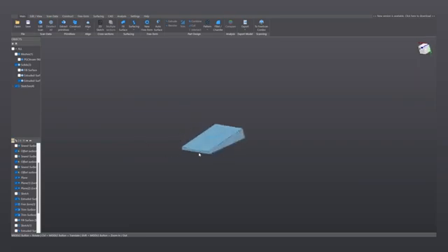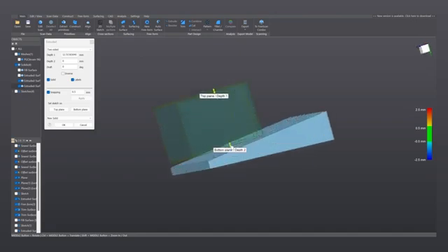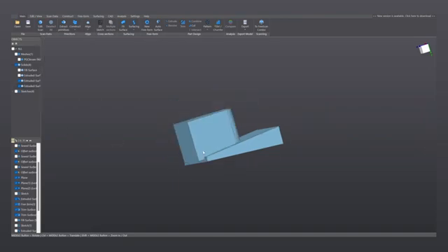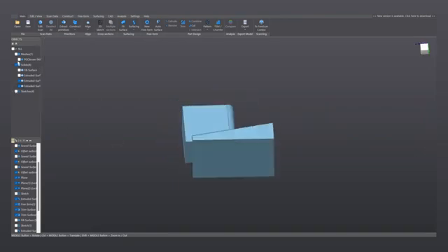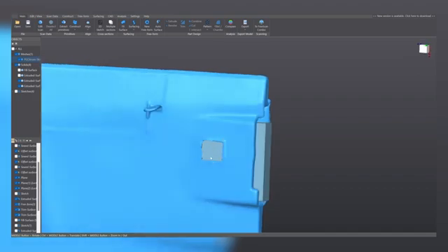All right, now we extrude this closed sketch till a certain height here, and here making sure that it extrudes until it's inside the other body. New solid is again selected, click on OK. And now let's focus on this square shape hole over here.